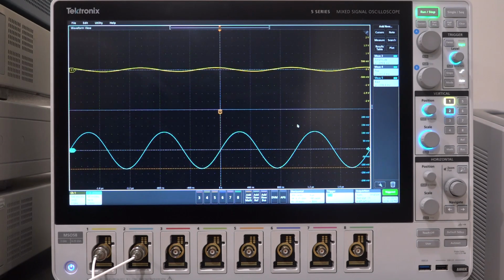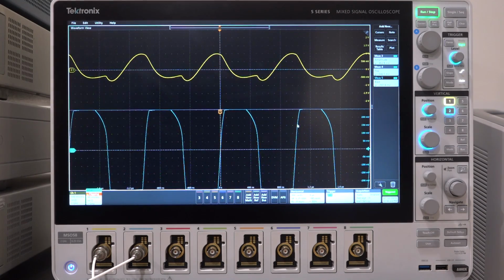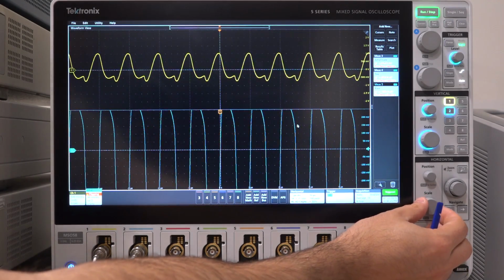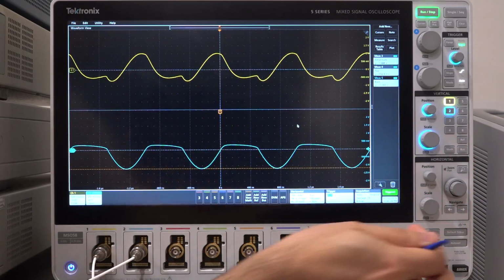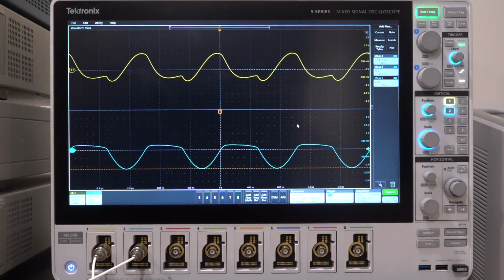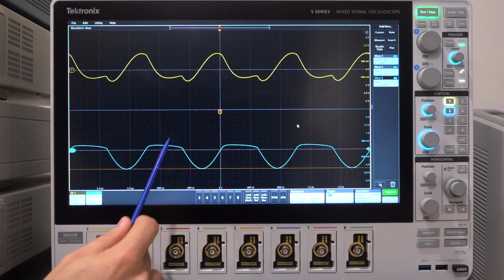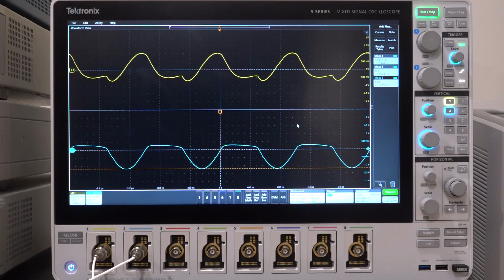Okay, let's go ahead and increase it by a factor of 5 like we did on the DUT originally. There it is. I'm going to change this because it's clipping the scope, and let's go ahead and do this again and check it out. Look at that. That's exactly what the function generator told us, that it is going to get clamped at the very top, but the bottom swing of the signal is going to be correct.